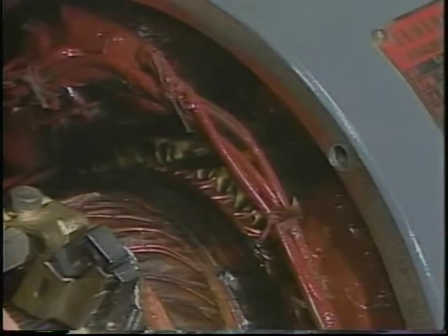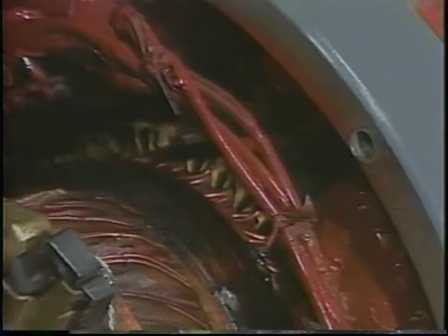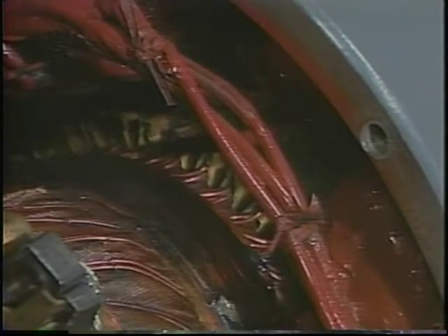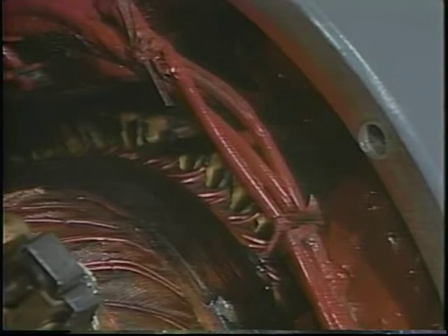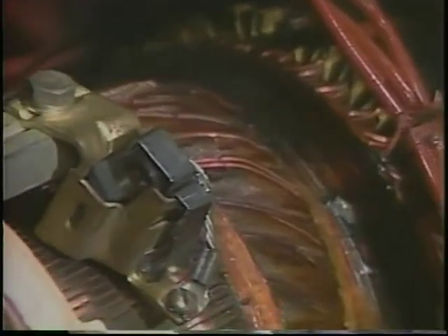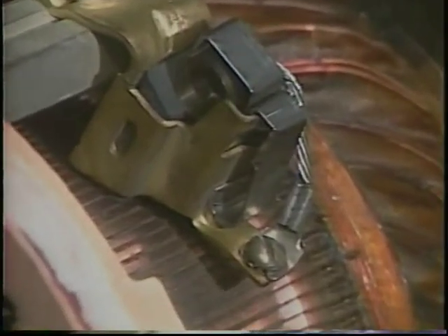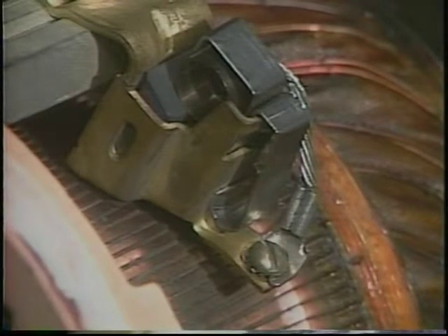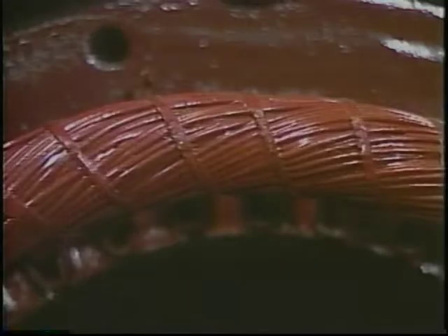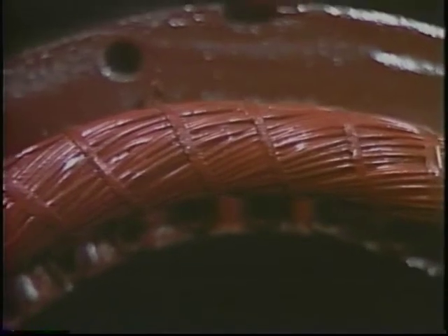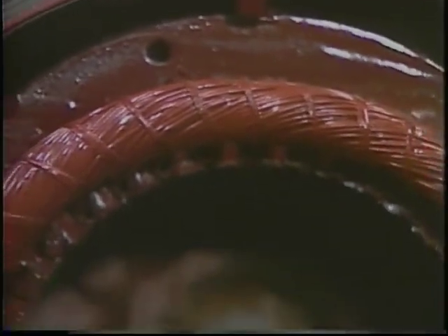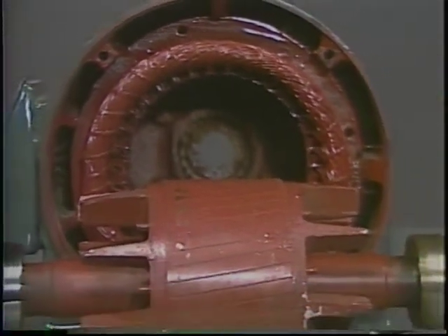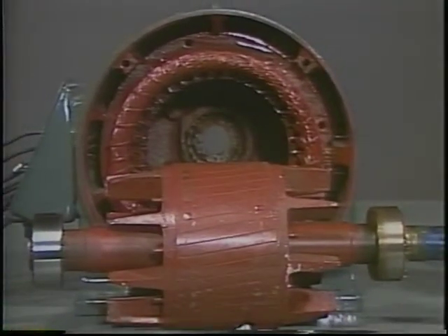All motors use electromagnets for either the rotor, the stator, or both. These electromagnets can vary quite a bit in wire gauge and number of turns. In a DC motor, the current in the rotor coils is reversed by the switching action of brushes sliding on a commutator. The second of these lessons deals specifically with DC motors. In an AC motor, alternating current is applied to the stator coils, so the stator poles reverse automatically. We will look at AC motors, both single-phase and three-phase, in Lesson 3.